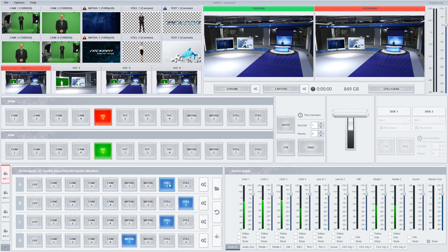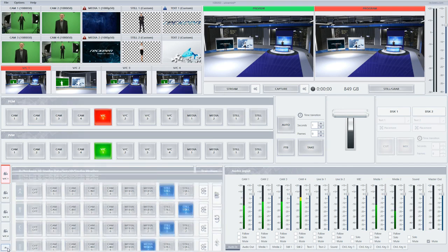In this studio, a source behind the desk is controlled with Mixer A. For a source on the left, we choose a content to display using Mixer B. As the source is placed on the floor, the designer assigned it a view from the camera. Further still, there is a third talent figure, a content for which is selected with Mixer C. A green field in the preview suggests this is a display screen to which we will assign a video or an image using Mixer D.